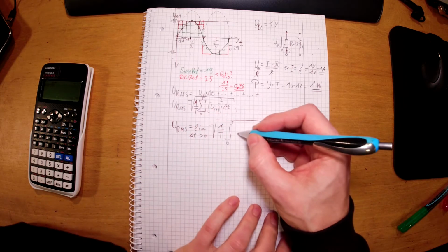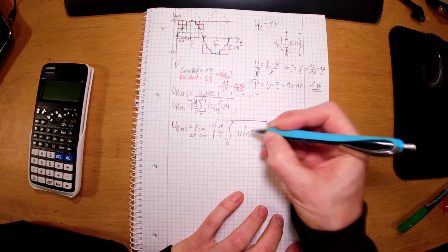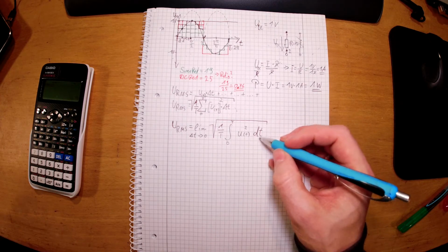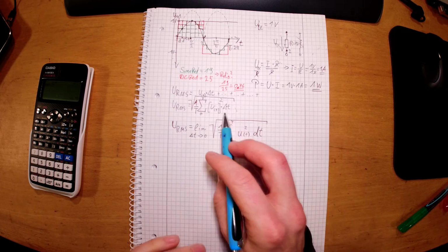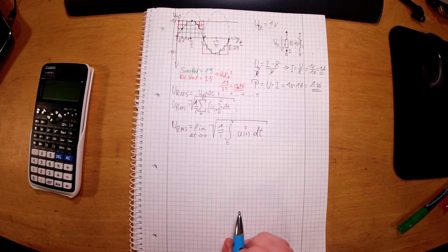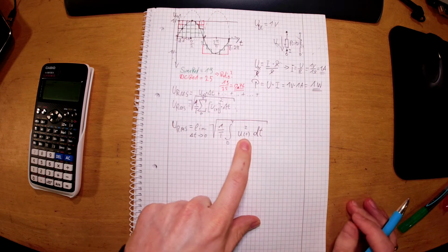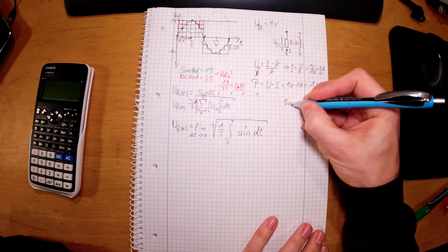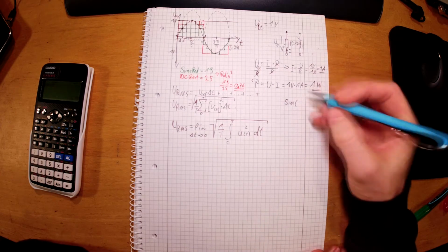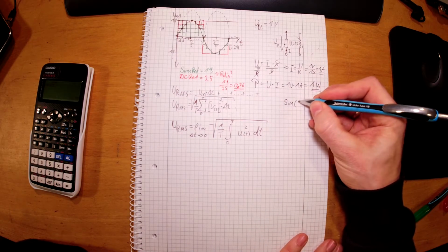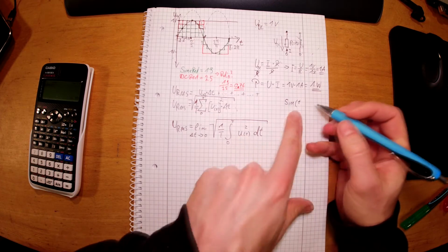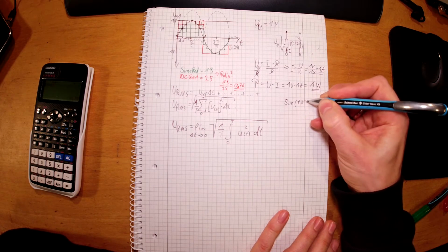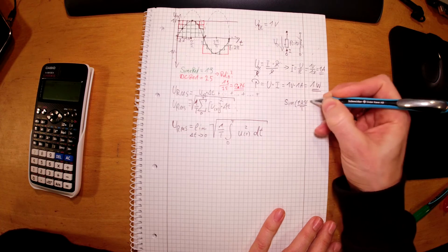We can fulfill that. So u squared of t, and then we use the differential, I think it is called in English, dt and not the delta t, because we are integrating. Okay? Now we need to know what our u of t is to calculate it really. And our u of t is a sine wave. Now it's maybe a bit complicated to understand why, but we're putting in our t because the argument of u of t is of course t. And we multiply it with 2 pi and divide it by big T.